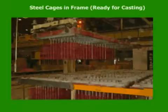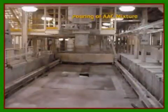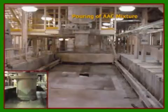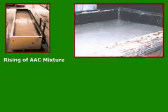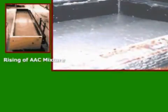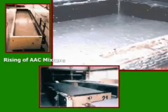Before we introduce the reinforcement cages into our mixed raw material mold, we protect the cages with a corrosion treatment. Here we pour the pre-mixed raw material in our forms. In this curing room, the aluminum paste finds its reaction. As you can see in the top right picture, there is a 3 to 4 inch space. Then after 8 to 10 hours, the reaction is completed and the AAC in the green stage has risen to the top of the form.